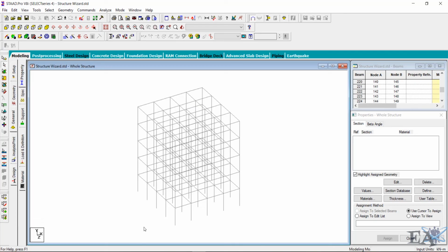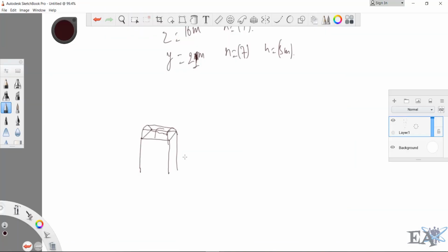For that you have to remember that if this is your frame, and suppose that this is the front view of the frame, then you make sure that the vertical members that you got of the truss lie perfectly on the columns, so that the load is transferred accurately to the columns and the beam doesn't take much of the load.